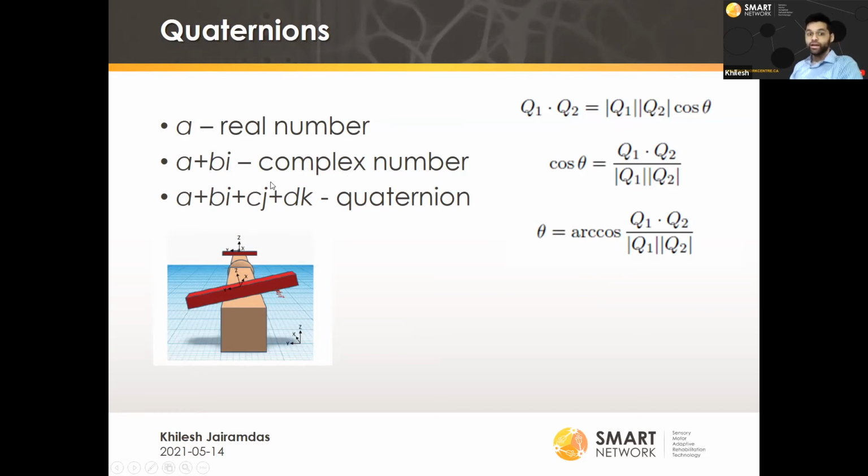So the IMUs are capable of outputting the four elements of the quaternion. And if you have those outputs from both of them, in combination with the black box calibration algorithm they come with, you turn them on, they take note of their current position, and you take the outputted quaternions, do a dot product, take the arc cosine, and that gives you the half angle. Theta is the half angle, so to get the full angle, you need to multiply that by 2.